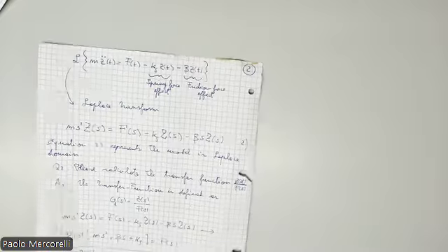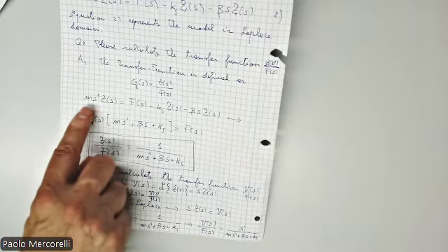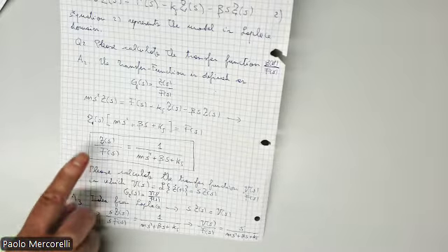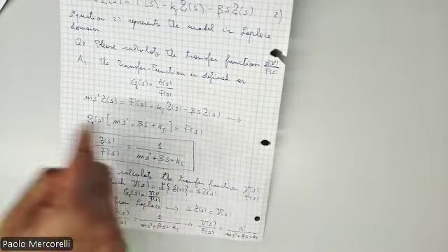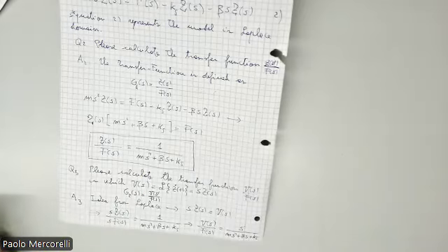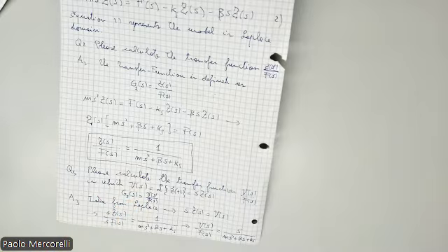Just repeating quickly what we did. And if you remember from this equation here, I can really calculate very quickly the transfer function because through algebraic calculation, I can obtain this, which somehow, or at least the denominator of this transfer function, reflects our differential equation, because our differential equation was m multiplied z dot dot, I don't know if you remember, plus beta multiplied z dot plus ks multiplied zeta equals f of t.